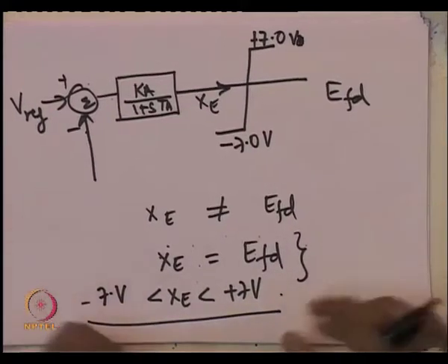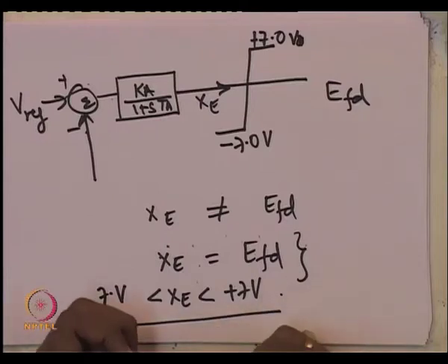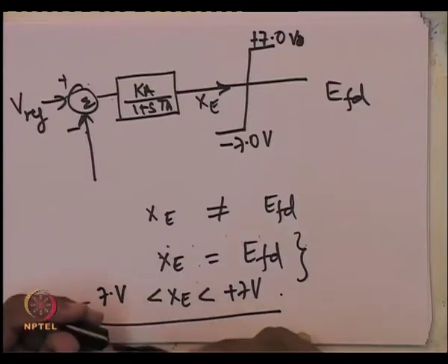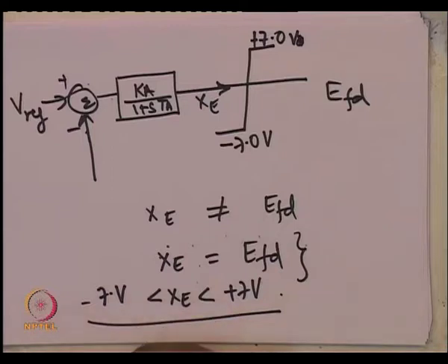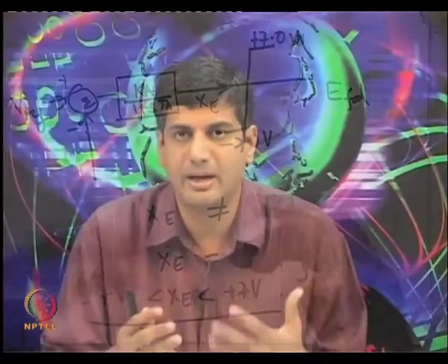If we had used a brushless excitation system, remember that we would get much more complicated equations for the excitation system. If I used a brushless exciter, the output would depend on dynamical equations associated with the excitation power apparatus as well. As I mentioned in the previous class, you need to look at the IEEE standard or several books which describe brushless excitation system modeling in detail.